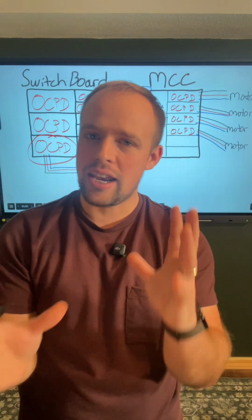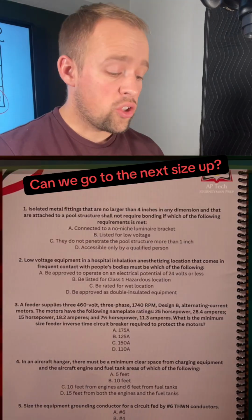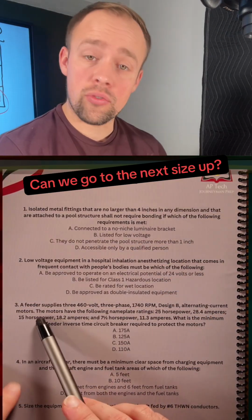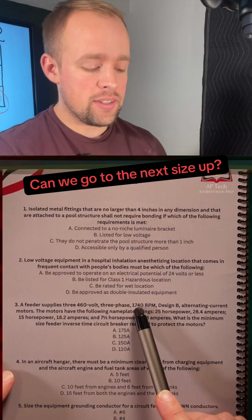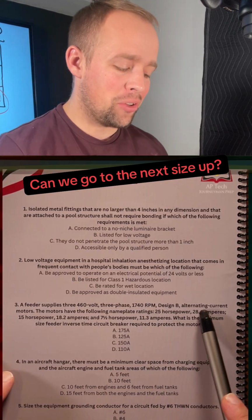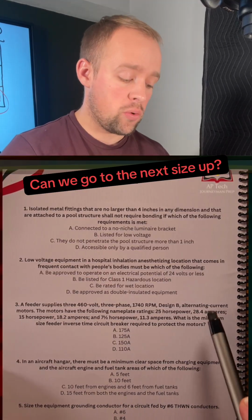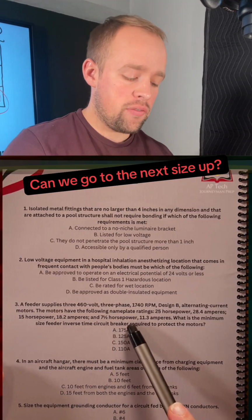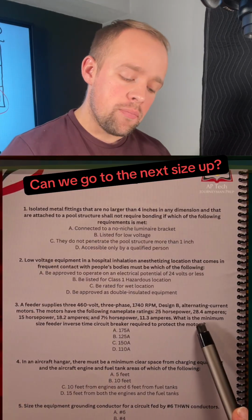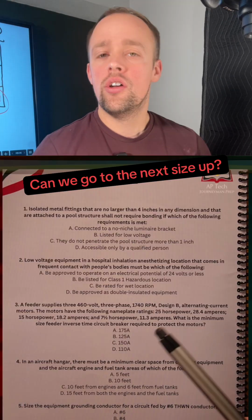Now that we have a picture and a little more understanding of what's going on here, let's get to the question. All right, so the question we're reading is Quiz 4, Question 3. It says a feeder supplies 3 460-volt, 3-phase, 1740 RPM, Design B, alternating current motors. The motors have the following nameplate ratings: 25 horsepower, 28.4 amps, 15 horsepower, 18.2 amps, and 7.5 horsepower, 11.3 amps. What is the minimum size feeder inverse time circuit breaker required to protect this motor?